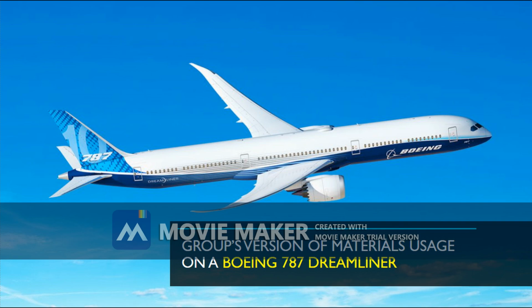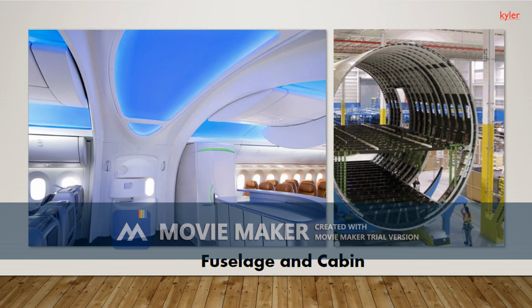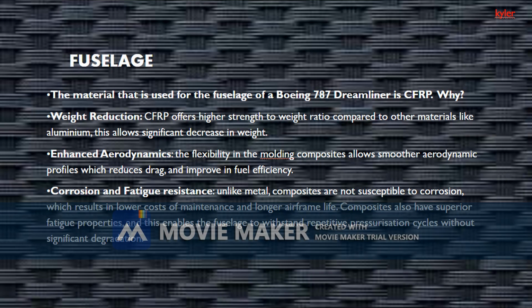This is our group's version of materials usage on a Boeing 787 Dreamliner. For the fuselage, the material that is best used for it is the CFRP. Why? CFRP offers a high strength to weight ratio compared to other materials like aluminum, so this allows significant weight reduction.